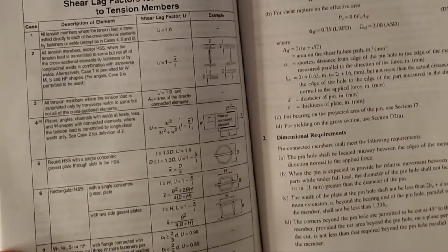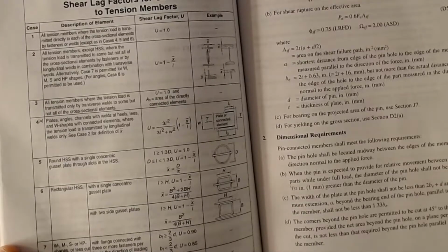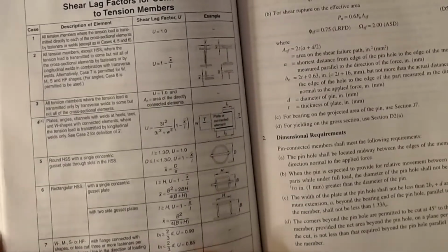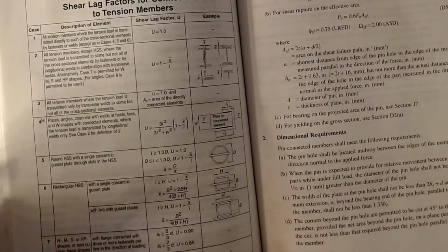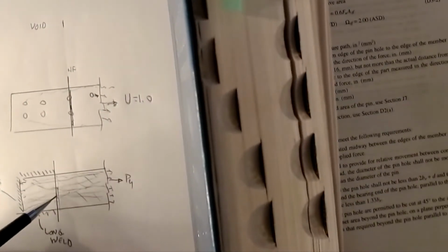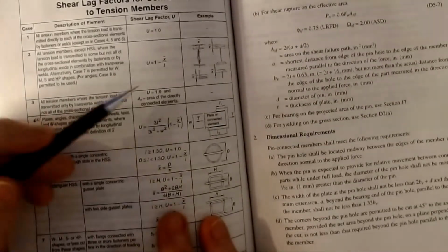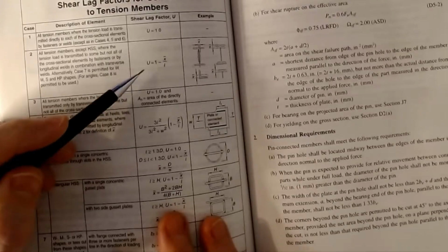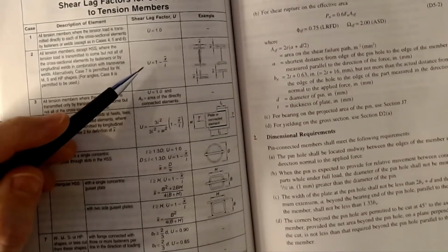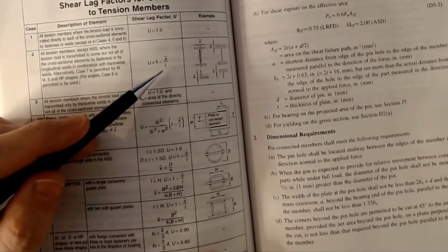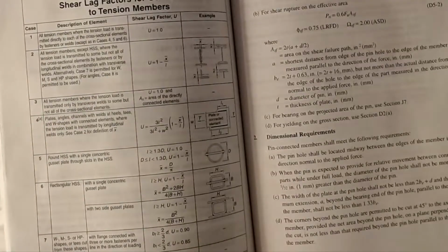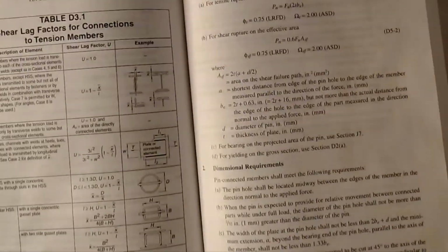So that's what it's saying. Now the formula that we use for this case too, because these welds are at different lengths, it's not fully effective, but it is better. So that's why if you've got a transverse weld in conjunction with longitudinal, I'm going to use the second case, this case 2, which is 1 minus x bar over L. Okay, and so the question becomes, well, what is x bar?